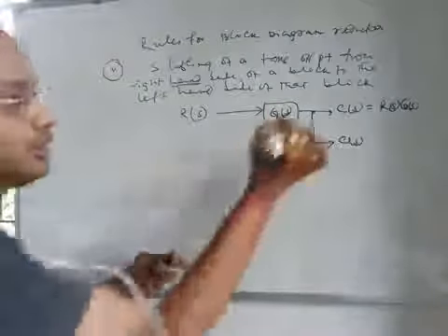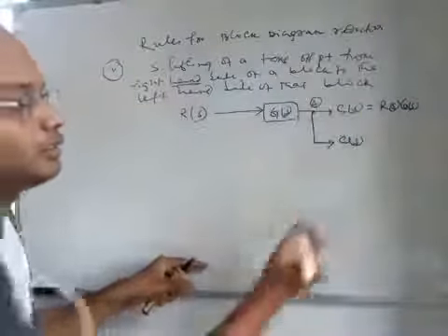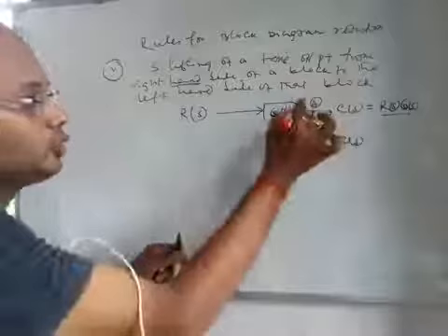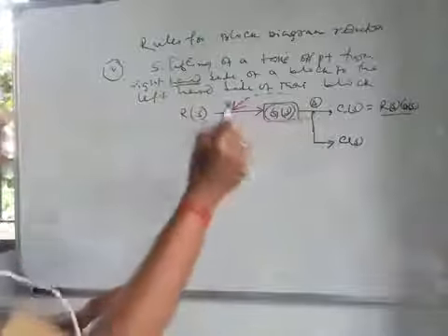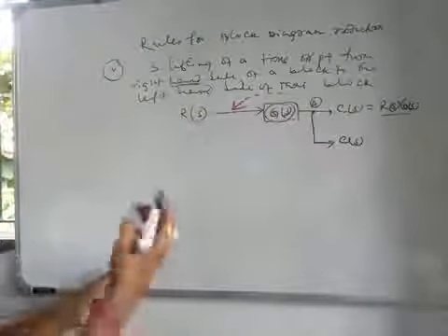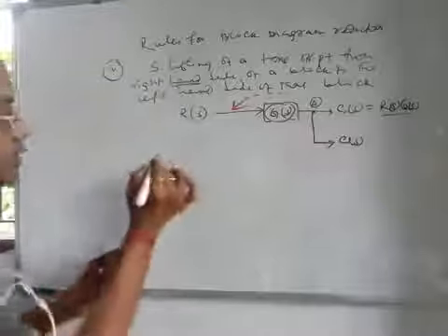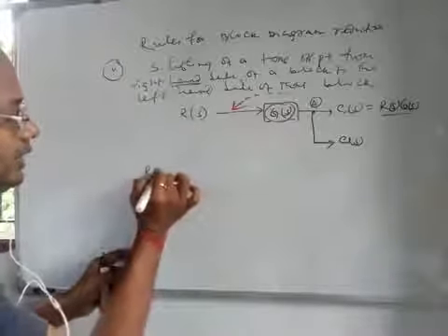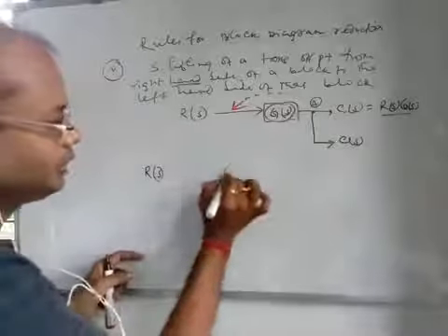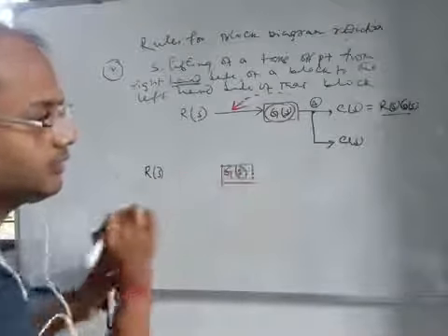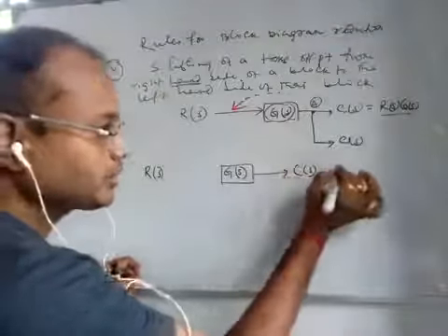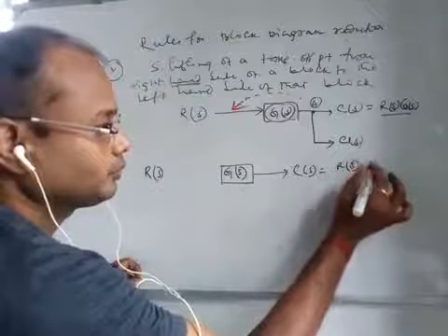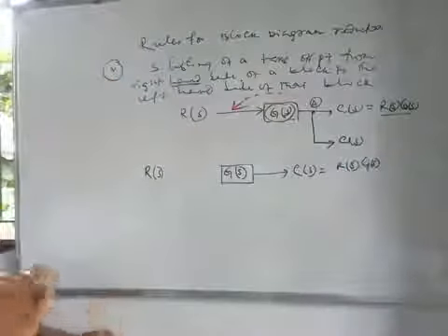This is your initial condition, A is there, right? So CS is equal to RS into GS. Now we have to shift this point to the left hand side of that particular block GS. From A to these positions you have to shift. So you have to keep all this remain same, RS, GS remain same. We will get CS. The value of the CS must be RS into GS. That is also fixed.